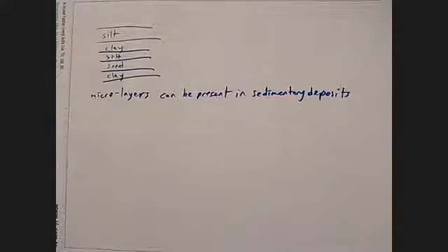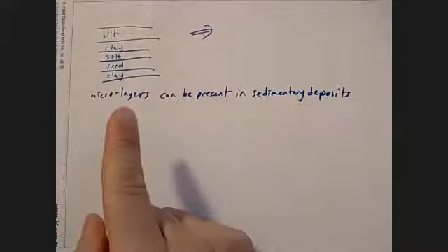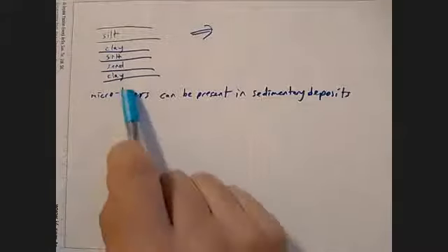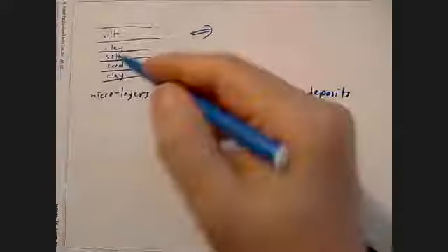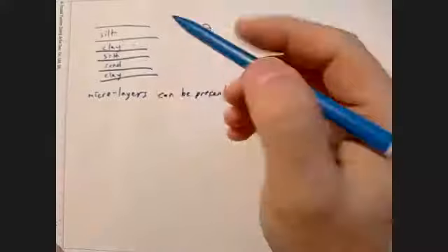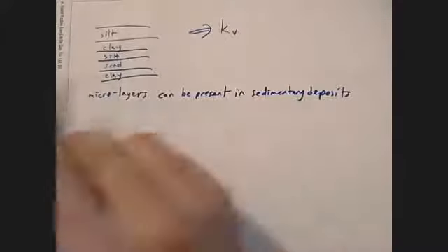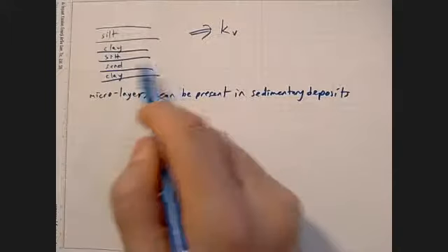Then, if you have something like this, then imagine you want to apply flow vertically or horizontally in this. For vertical flow, your flow will still have to go through all these clay layers. But for horizontal flow, if you are trying to just make horizontal flow in this, there is a sand layer, so all of the flow will just prefer to go through the sand layer.